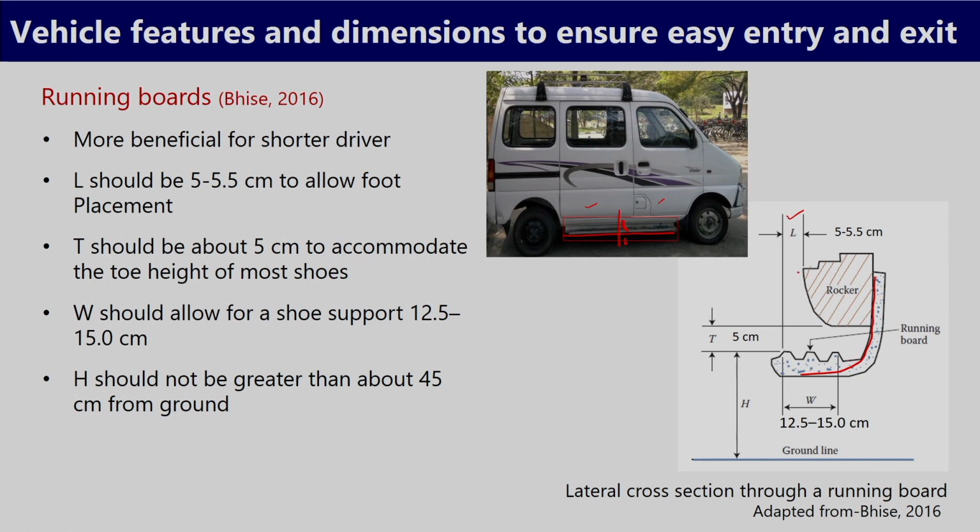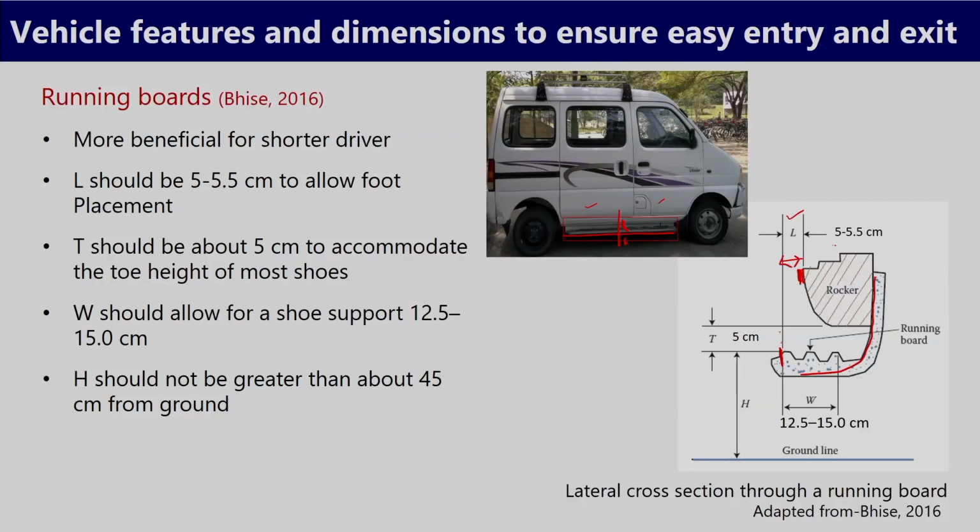So, now the lateral distance between the outward edge of the rocker panel and the front edge of the footboard or running board should be at least 5 to 5.5 centimeter. It allows foot placement during climbing inside the vehicle or getting down.